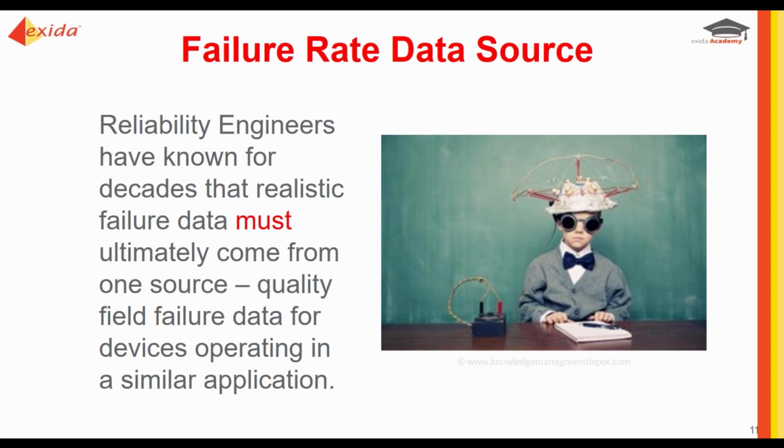Once again, high demand and low demand mode of operation. You always want to make sure you're comparing an apples to apples comparison and you're not crossing those. Same with clean and severe service, close on trip, open on trip applications. All of these need to be considered when you're looking at your field failure information or your data sources.